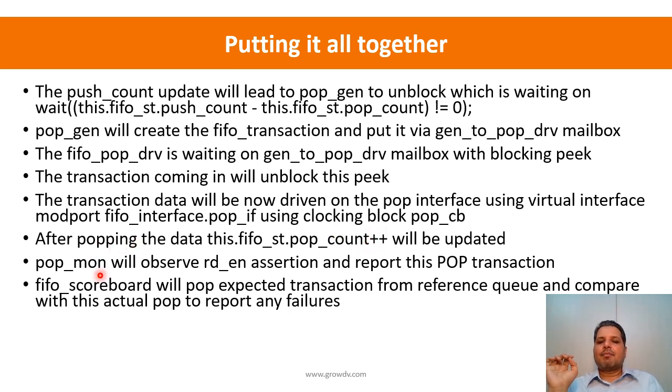And while this is happening, this is all happening in parallel, right? So pop monitor is still active, and because it has its own run thread, which we had launched in the environment, this keeping track of threads, multiple threads, is a very important part of looking at any test benches. So we have many times emphasized, even during that Verilog refresher, that time and concurrency is a very important concept, and many people fail to understand this, and it creates a lot of issues.